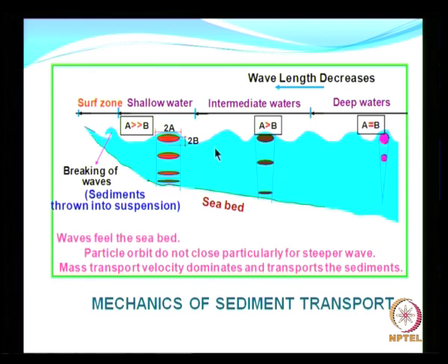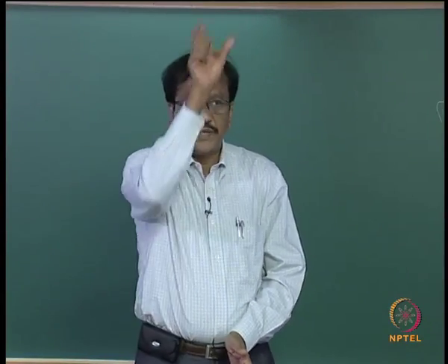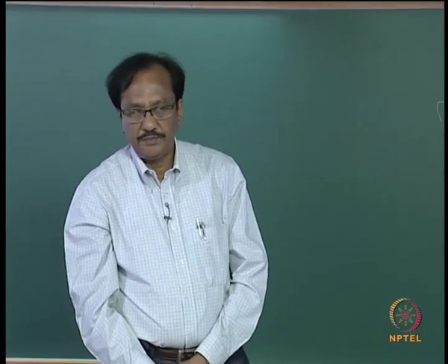But once the waves leave the deep water situation, once it enters the intermediate depth conditions, you know that it starts feeling the bottom, and the horizontal displacement will slowly reduce as you go towards the seabed, but still the effect of waves will be felt on the seabed in intermediate water depths.